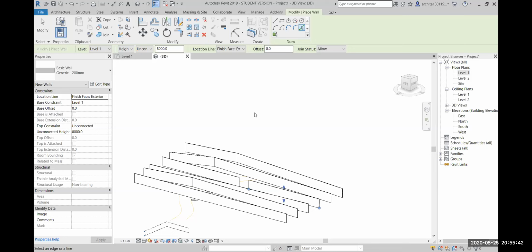But you know what, I'll tell you, although you will learn later that you can actually make the entire thing from scratch in Revit itself, like the 2D drafting also. But let's say if you have it in your CAD file and you want to use that as reference, always before bringing it to Revit, clear the file, as in clear the unwanted things.